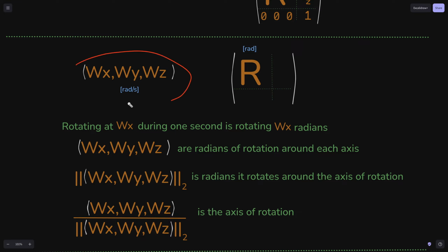So those angular velocities are related only to the rotation matrix, or in the representation when you have translation and quaternion, that would be the quaternion. Okay, but translation plays no role here. This is important. Okay. So, and what does this mean? Well, this says it's radians per second, but let's think about it. We are rotating using this constant angular velocity for a second. So what does this mean? This is an almost primary school problem.